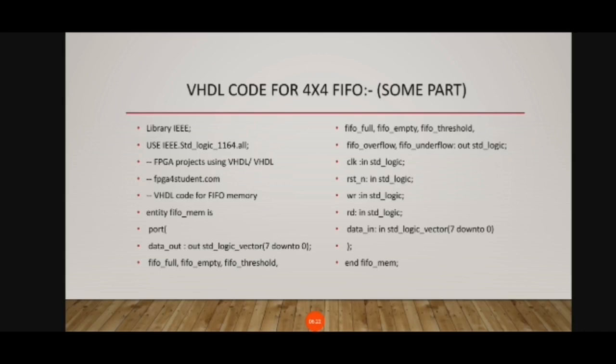In this type of modeling, the behavior of an entity as a set of statements is executed sequentially in the specified order. Only statements placed inside a process, function or procedure are sequential. In structural modeling, an entity is described as a set of interconnected components. A component's instantiation statement is a concurrent statement.